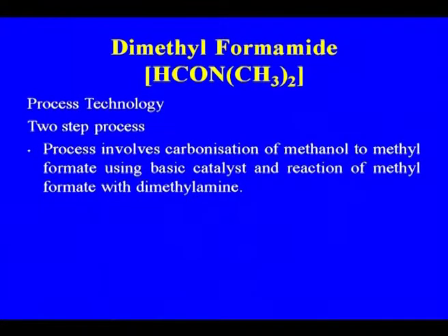This is the two-step process. The process involves carbonylation of the methanol to methyl formate using a basic catalyst, and reaction of methyl formate with dimethylamine. So, this is the two-step process which we are using for making of the dimethyl formamide.